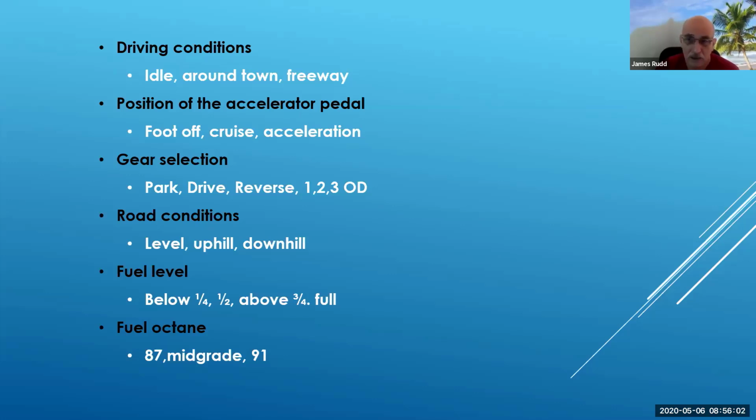But also the octane: if a car is engineered for a 91 octane, it needs to have that 91 octane. We can have ill effects if it doesn't. Most of the manufacturers are putting out several models of vehicles that run on 87 octane, which again is a little bit cheaper, and it does help not worrying about it being the right octane. That brings the other discussion about can I put in a better octane? Yeah, you can. In a way, you're just kind of throwing your money away. So just things to think about.